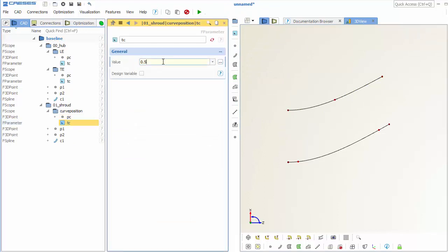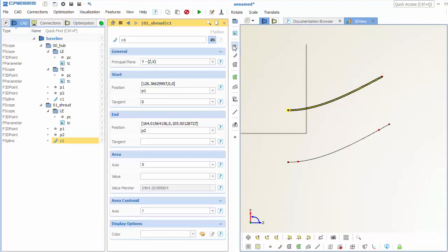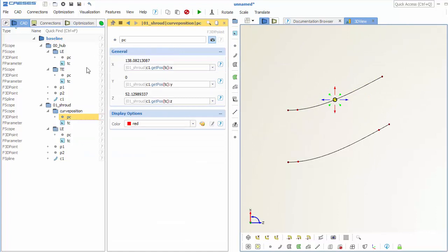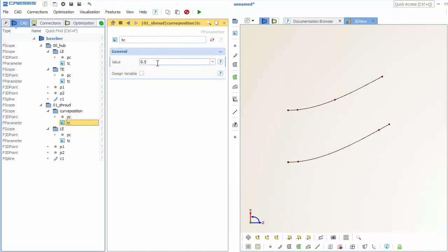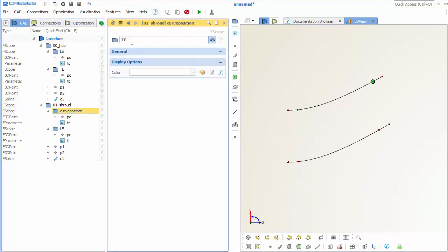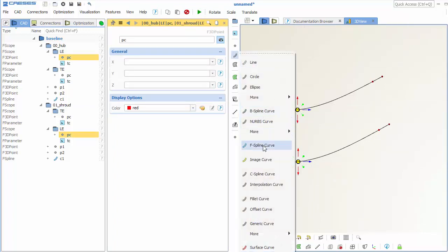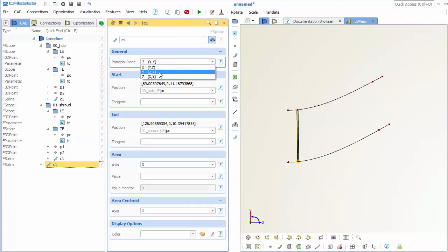And we do the same for the shroud contour as well. Just have the leading edge position here, select the curve, create another point and change the curve position on this curve. So then, maybe we rename it. So then we have these 2 points and create a connection in between.